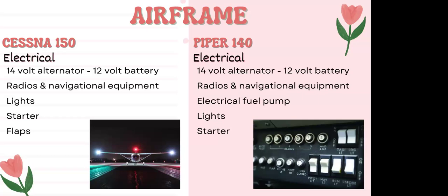The other reason that can be helpful is that if you had an electrical fire, which is pretty uncommon, and I mean, by pretty uncommon, I don't know the last time I heard of anybody having an electrical fire, but if you were to have an electrical fire, again, you don't want everything connected because if your strobe lights are on fire, you don't want your entire radio system to start catching flame. So if you turn everything off and isolate that system the way that the designers planned for you to be able to do, then you're able to mitigate and isolate risk.